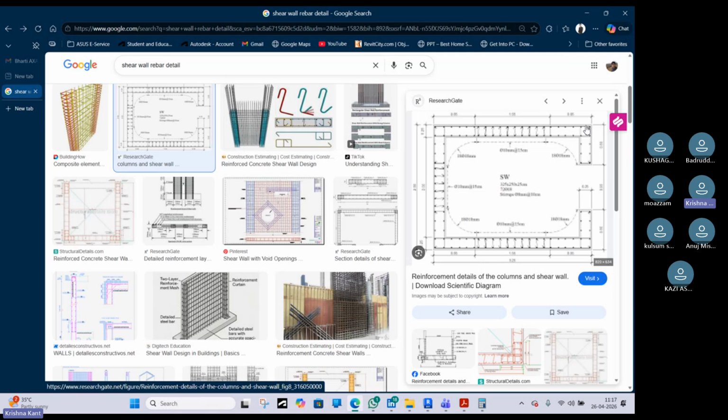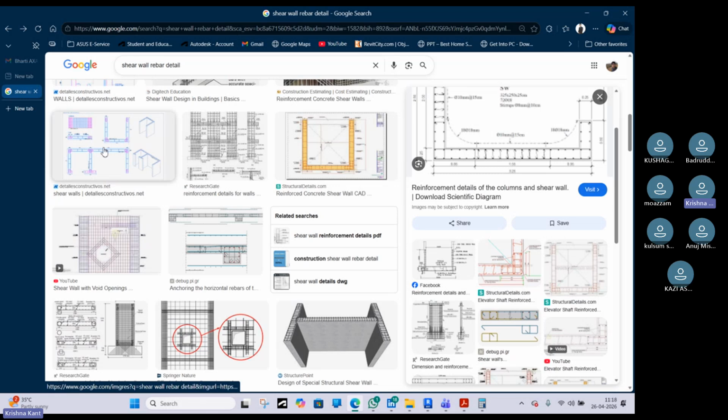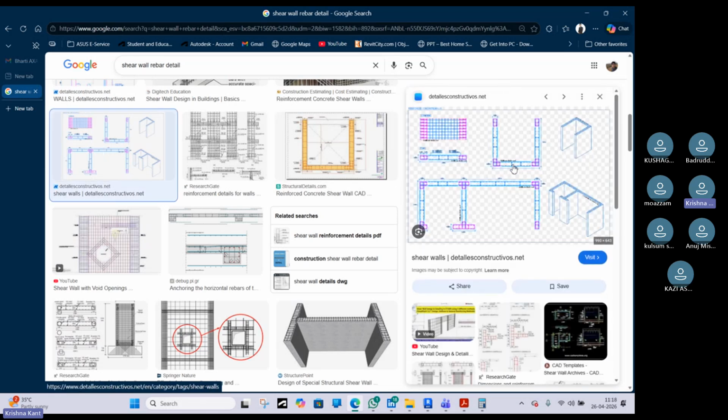That vertical reinforcement you can place with spacing. In a shear wall, it is fine to provide it with spacing, because at the bottom in the foundation, the extension of the main bar is all along the horizontal wall. Maybe on the corner you can provide a 45-degree bend, but throughout the wall you can provide unidirectional extension. That is it. So when you have to detail a shear wall, it is quite easy.